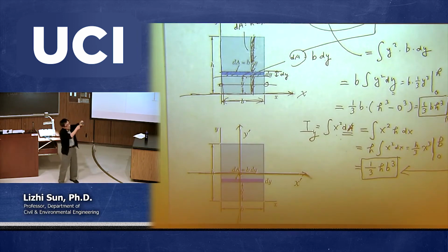Because look at this one, if this is a cross section, this is h, and this is a tiny b. So h is much larger than b. If you go back to look at this b times h cubed, imagine a number, compared with this one with the same cross-section area. However, this becomes your new h, and this becomes your new b. So this h is very tiny, and b is much bigger.